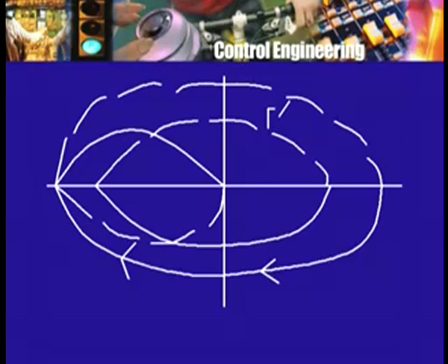Now, this is not the whole of the image contour gamma prime. So, I have to complete it by taking its mirror image. So, let me draw this dashed line to indicate the mirror image. So, this is one part of it, this is the other part of it, and this is corresponding to that semicircle business, a point which is very close to the origin, or the part of that curve is very close to the origin. So, I can essentially show it as going through the origin. So, this is going to be the polar plot, or the entire Nyquist image of the Nyquist contour. This is going to be gamma prime.